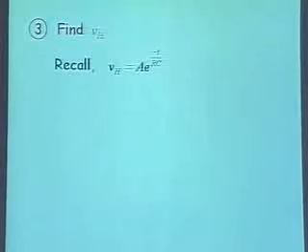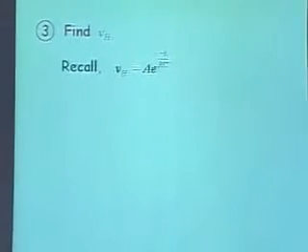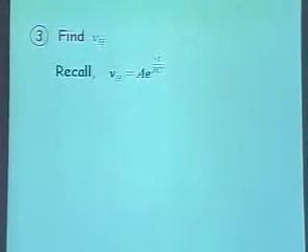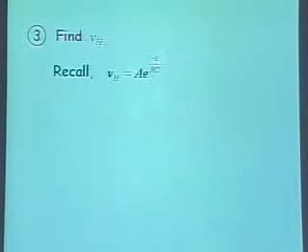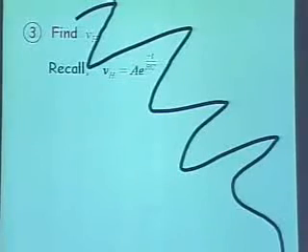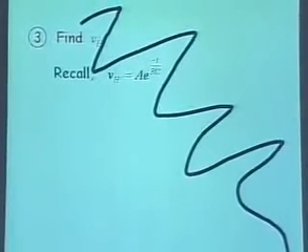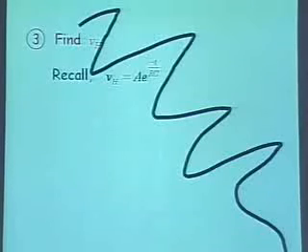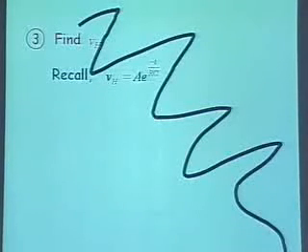But recall that the homogeneous solution for our RC circuit is of the form A e to the minus t by RC. This means that as time becomes very large, this part goes to 0. As time becomes large in the steady state, and remember I care about the steady state, this goes to 0. And so I don't care about the homogeneous solution. Isn't that fantastic? For most of the circuits we will deal with, except for purely oscillatory ones, the homogeneous part dies away. You have something like e to the minus t or whatever. It just dies away. It's gone.